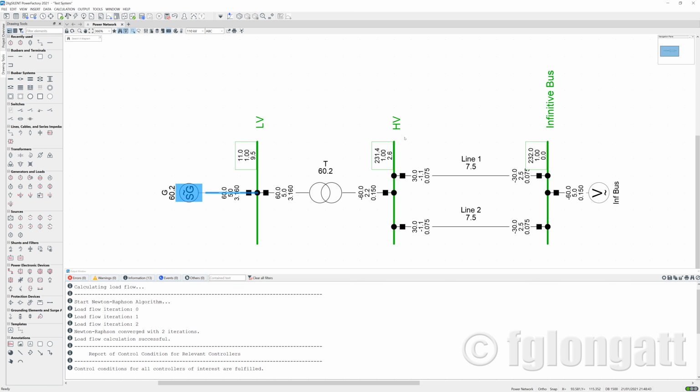Okay, to be precise about how the active and reactive power move, I can suggest that you use some functionalities here inside PowerFactory. PowerFactory, a couple of versions ago, included the possibility of adding some arrows in the single line diagram, and those arrows can represent the power flow direction.